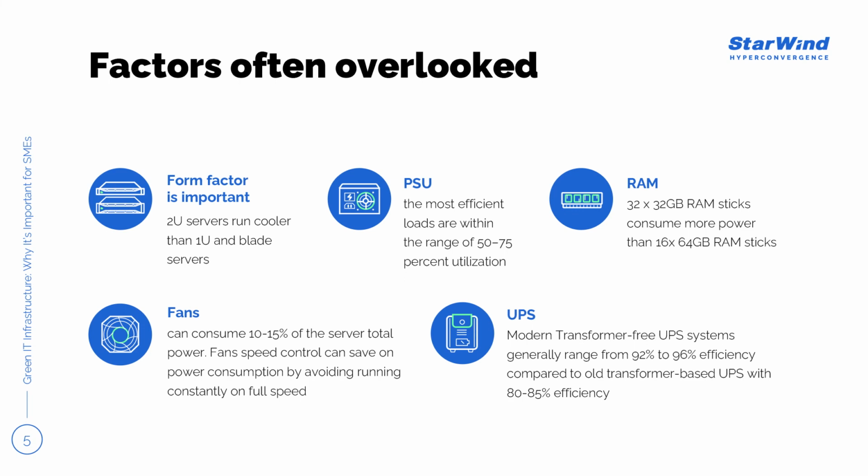because of course we want our power supply unit to cover more workload than you would actually have, but still try to hit that sweet spot between 50–75% load, or also invest in a better PSU with 80+ platinum or titanium certification that provides efficiency at around 90%, even on lower ends of the spectrum, compared to bronze or silver that deliver around 80–85% efficiency on the lower and higher ends.